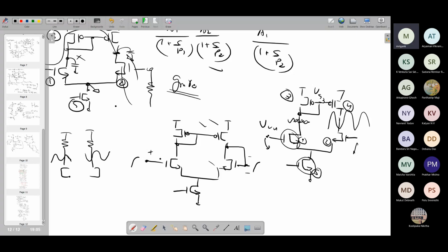So here, as we have seen, it is a diode connected load. We have analyzed the two paths separately also. Here the gain is small, whereas the final gain is much larger. So we can assume that this DC is almost the same. Even if you are applying some input signal, this remains close to the DC value. Therefore, whatever VG3 is required to support ID by 2, as compared to that VG3, the maximum VCM will be VG3 plus VT of 1.